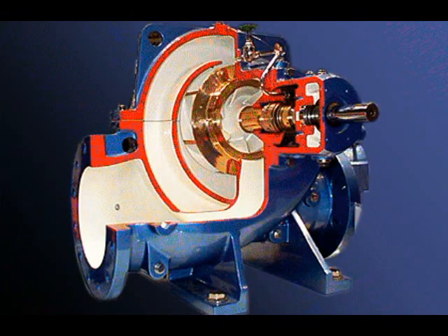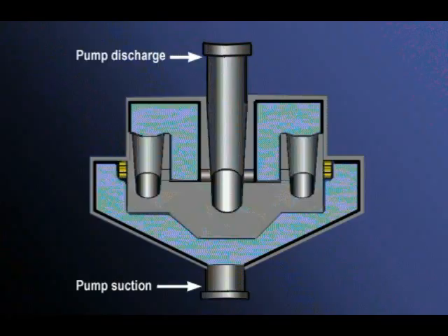Here is a photograph of another centrifugal pump called a double suction pump. On this pump, the intake and discharge are both normally below the center line of the pump. This gives greater pumping volume than the same pump with single suction. Although additional stages will not affect the amount of liquid pumped, they will increase the pressure at which the liquid is pumped. This means that multi-stage pumps are used when high pressures are required.